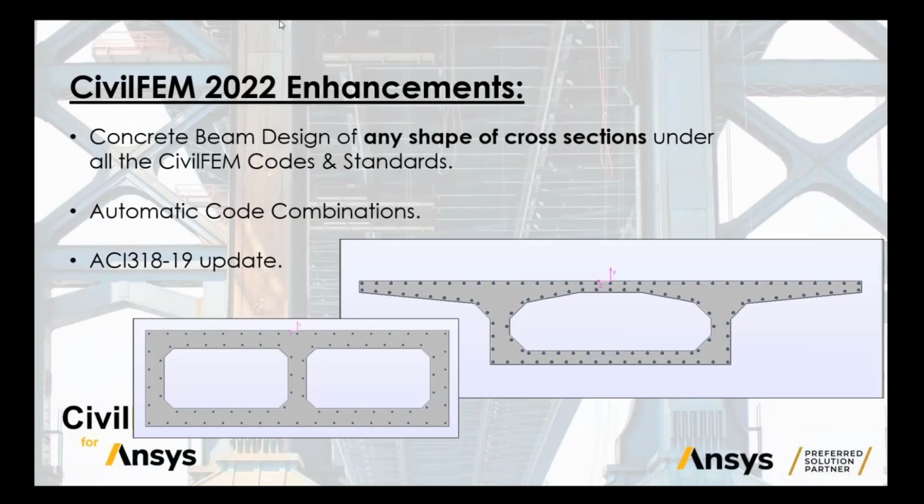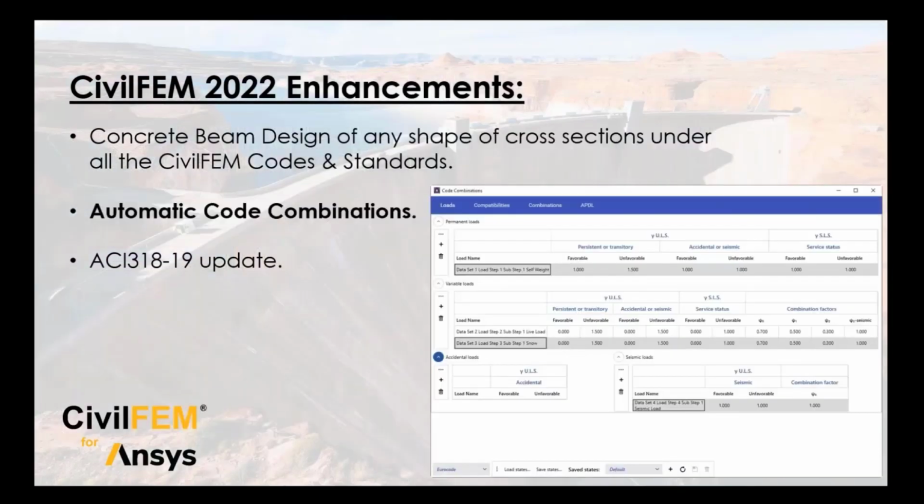We have predefined a minimum reinforcement amount in all the phases, with rebars of 12 millimeters diameter and a spacing of 30 centimeters. That is the minimum reinforcement amount, and we have placed it around. What CivilFEM will do is increase the reinforcement groups that are needed to fulfill the codes.